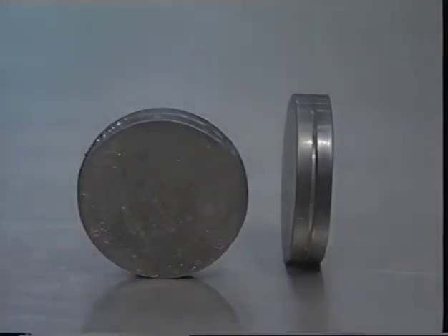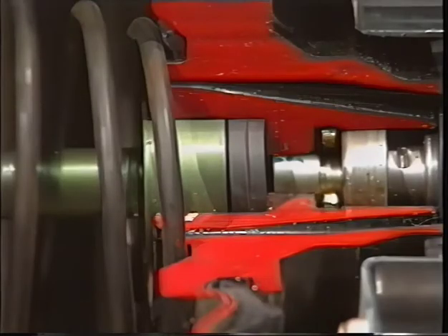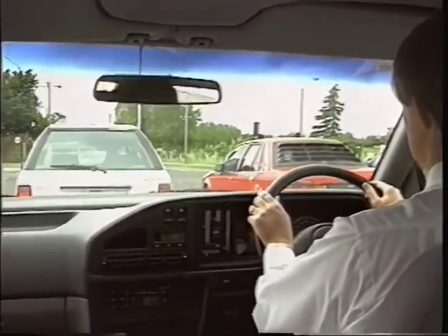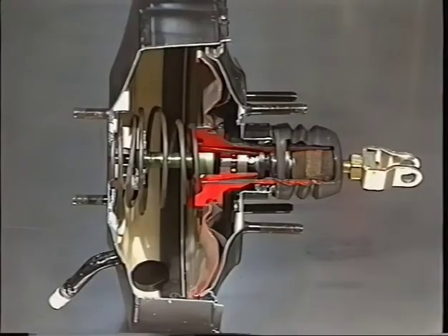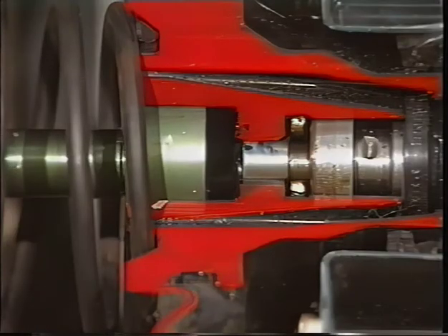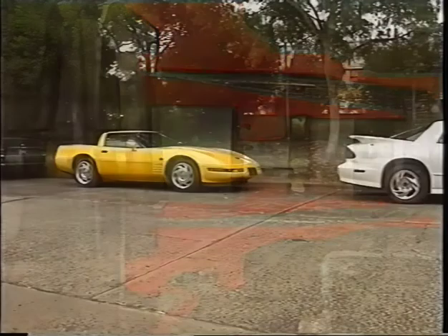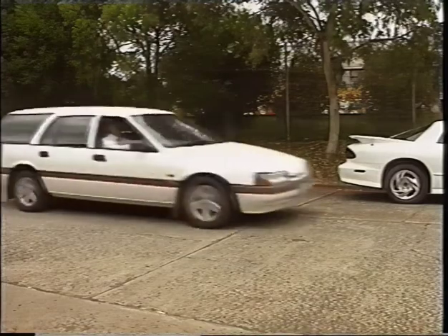Following this, we looked at the reaction disc, a small rubber disc that sits between the valve and the booster output rod. This small disc's purpose is to allow the driver to control the amount of boost applied to the brakes, and we noted that if it had become dislodged and fallen into the bottom of the booster, then the output push rod would move backwards to take up the clearance, resulting in greatly increased pedal travel and overly sensitive brakes at low speed.